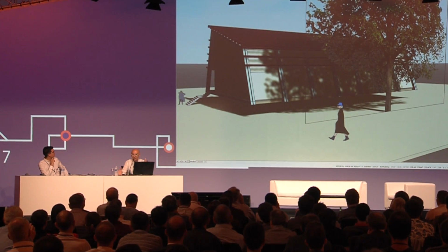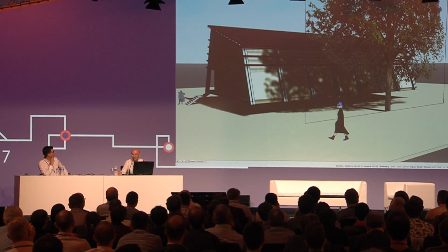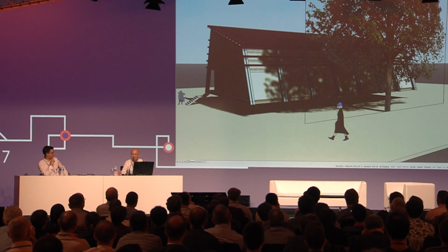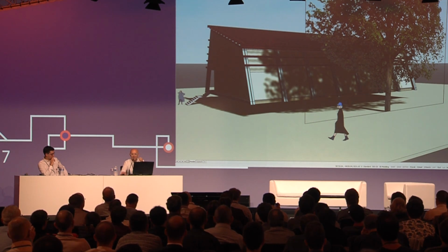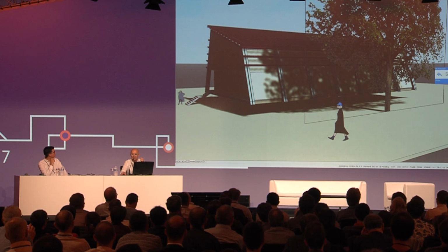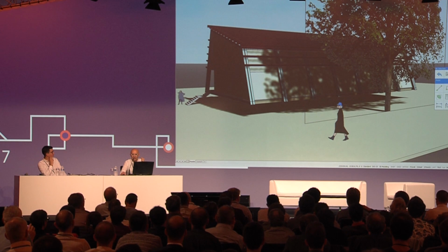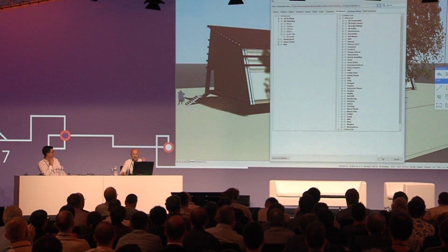Now, am I in trouble, like in most applications, when I no longer have a menu, or a toolbar or a ribbon or a command line? Oh, not with BricsCAD. You can continue. You know you have the quad wherever your cursor happens to be. And if, for instance, in my drawing menu, I would like to have another tool, like a spline, that is not there, I can customize quad items easily.